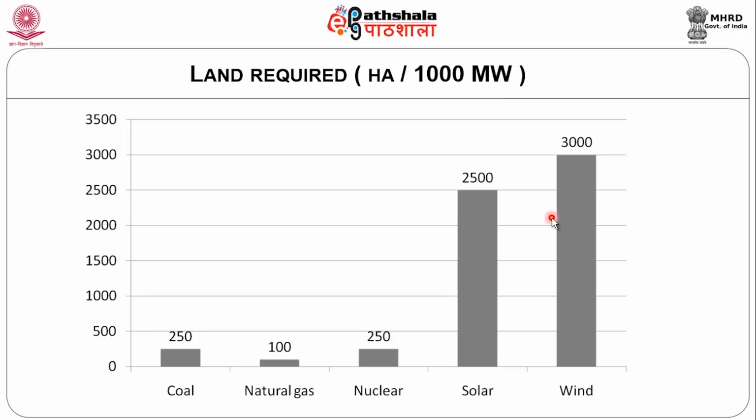And people are doing further research in order to increase the capacity factor, for which they have to select the right site, where the annual wind speed should be in the order of 10 meters per second. If most turbines are operated at rated power speed, definitely the performance will be very interesting.